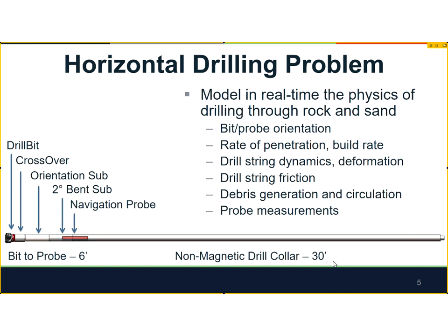And then the way they steer is this. You can't tell on this scale, but there's a slight bend in this piece, and so they basically can orient that bend. If they orient it up and they push, then when they're drilling, they're basically going to climb and build angle. And they have the ability on their gauges to know how that bit is oriented underground, however far away.